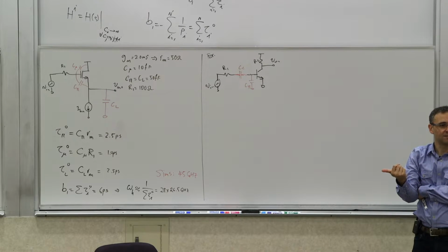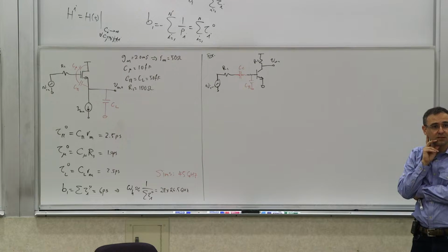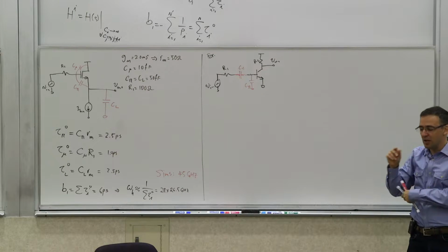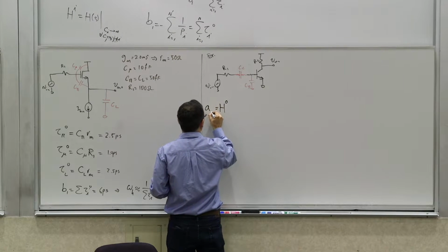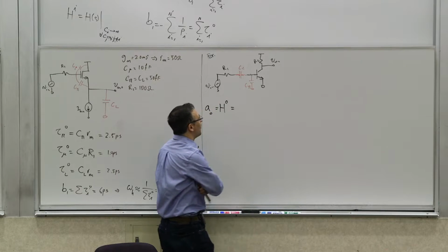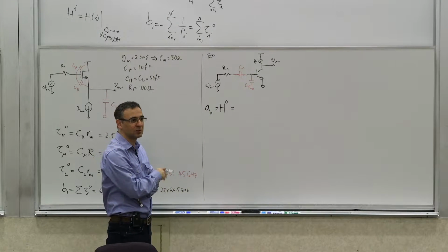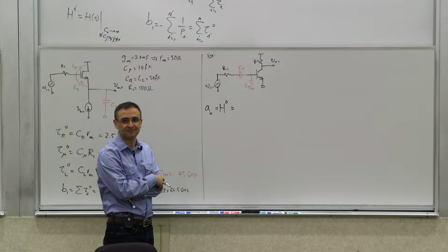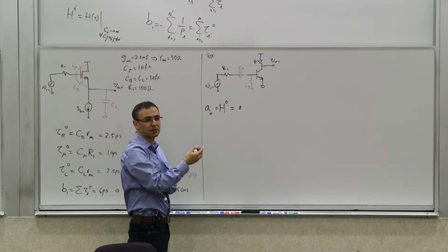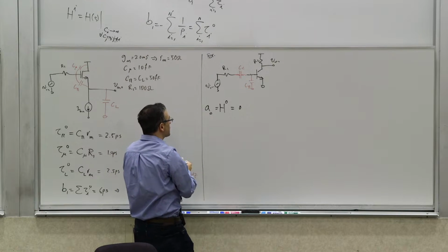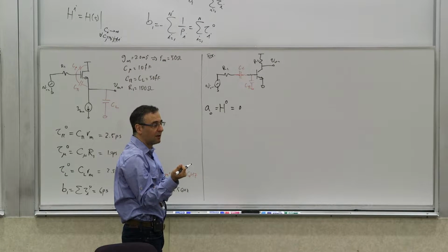We know that. What is its gain at DC, at its very low frequencies? What's the gain of this amp? If I ask you what is H0, which is A0, the low frequency gain, how do you calculate that? You set all the elements to 0 value and you see what comes out. What is it? 0, right? Because this is going to be an open circuit. There's nothing going to go through. So you can see that its low DC gain in this case is 0, right?